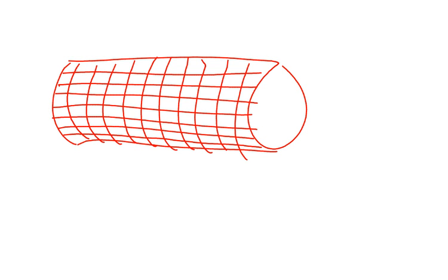So remember from last time how we described normal and shear stresses, right? Under a normal stress, those squares just elongate into rectangles, or they get shorter, they get compressed into rectangles. But under a shear stress, you might remember that right angles become acute or obtuse, okay?